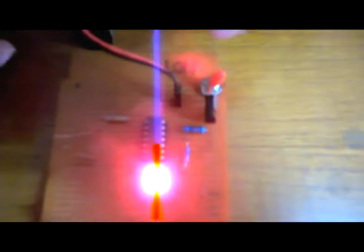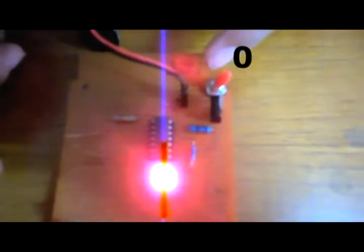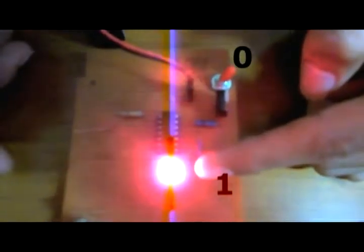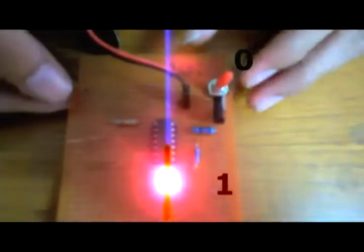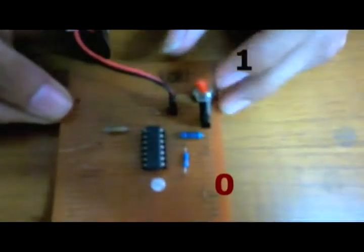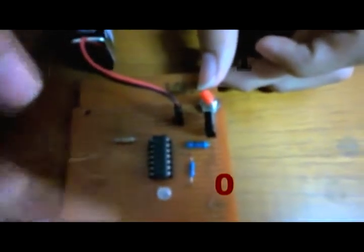So now the logic value at the A input is low or 0. So the output is high voltage or 1. So the LED will light up. But if I change the logic value to 1, the output will be 0, or the LED will be turned off. Okay, that's all about my project. It's all about the AND, OR, and NOT logic gates.